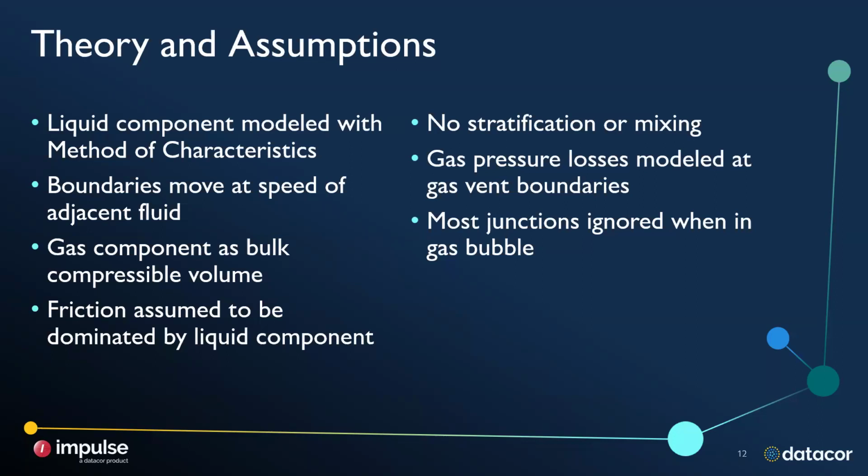So you don't have to have fine modeling in all of those, but at least with the bubbles passing through it, you should. And potentially more for air valves if the valve is chattering, because as it's opening and closing, you could have smaller bubbles than if you just have an exit valve that's always open or something like that. So keep that in mind if you're modeling a system with air valves or vacuum breaker valves.